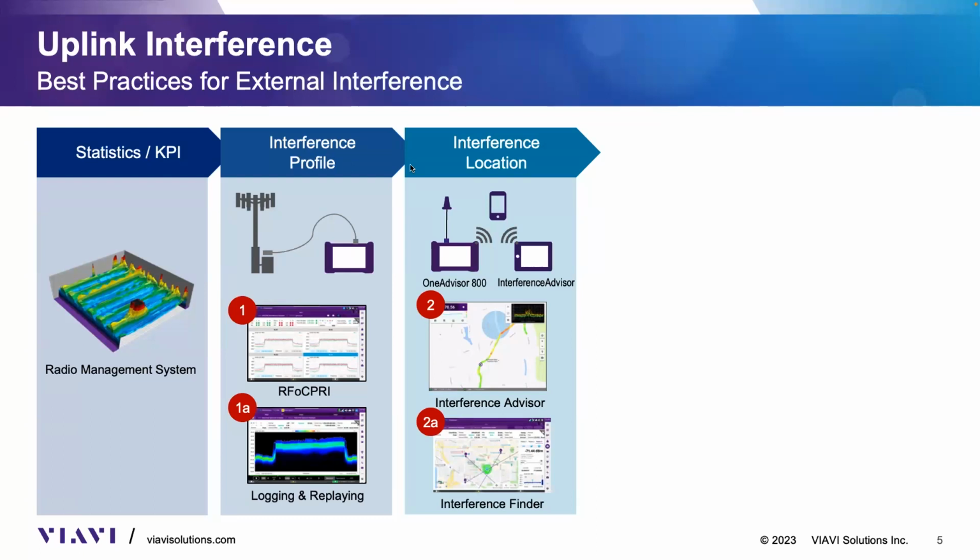done in a conventional way with triangulation using a broadband antenna. That's okay. It takes more time, certainly, but sometimes I've seen people still doing it. It's fine when you have an environment that doesn't have a lot of buildings, because certainly one of the things you want to avoid is a lot of reflections. If the interference is reflecting off buildings, then we're going to be doing a lot of multiple triangulations that sometimes are going to be pointing to a different location from where the interference is.